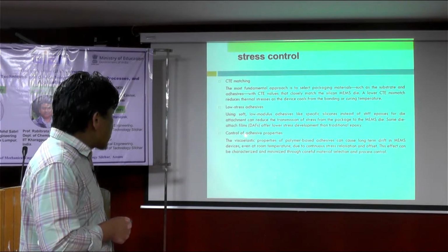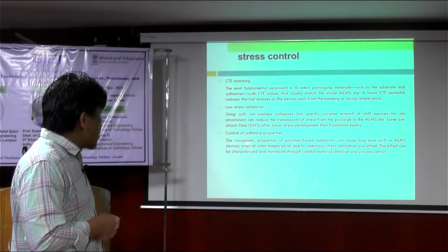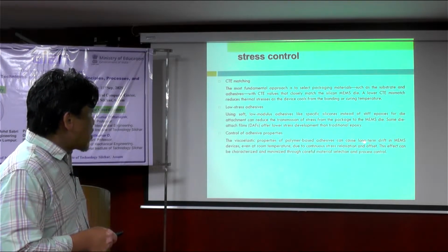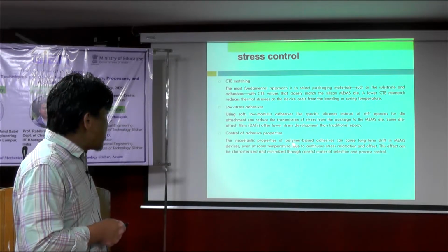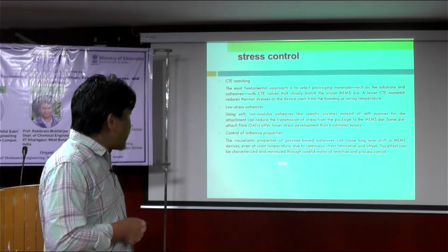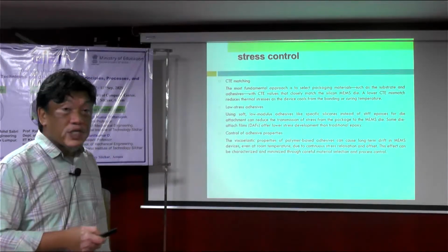And the next is control of adhesive properties. So the viscoelastic properties of polymer-based adhesive can cause long-term drift in MEMS devices, even at room temperature, due to the continuous stress relaxation and offset. This effect can be characterized and minimized through careful material selection and also process control as well.